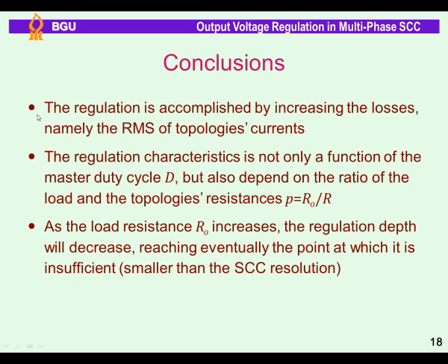So, the regulation is accomplished by increasing the losses. Besides the master duty cycle, the regulation characteristic is also dependent on the ratio of the load and the switch resistances. As the load resistance increases, the regulation depth decreases, and at very light loads the regulation ability is lost.